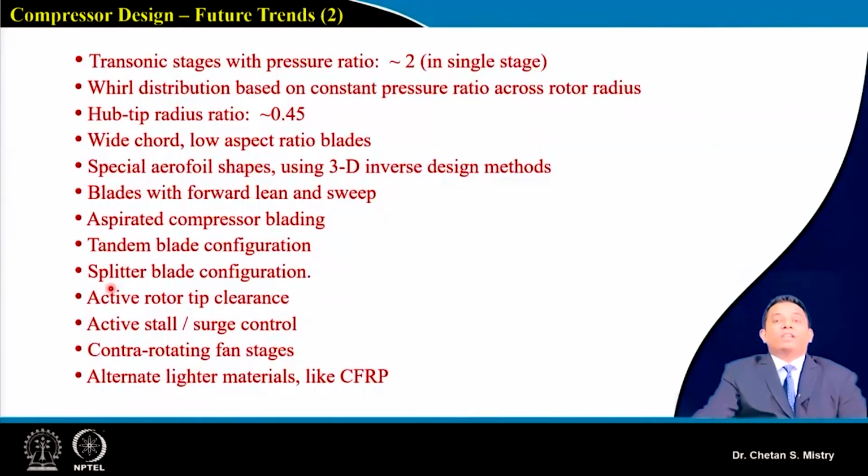That gives the benefit of very high exit area. When we have exit area high, there are more chances for our flow to get separated from the pressure surface or the suction surface of our blade. So by incorporating this splitter blade, it is permitting the pressure rise to go even higher.